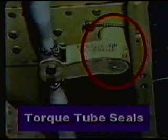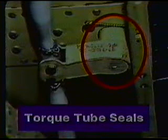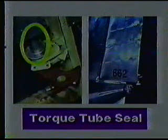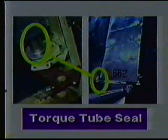Several pressurization seals are used in the flight control system. Cable seals include those used on the trim cables, usually referred to by the name of the cable lay seal, as in aileron trim cable seal. The larger seals that are used on the elevator cables are called the elevator cable seals. Rubber O-ring seals are used on the aileron bow tie torque tube and bearing housing. These are called the torque tube seals. There is also a rubber O-ring used to seal the rudder torque tube where it penetrates the fuselage vessel, called the torque tube seal.